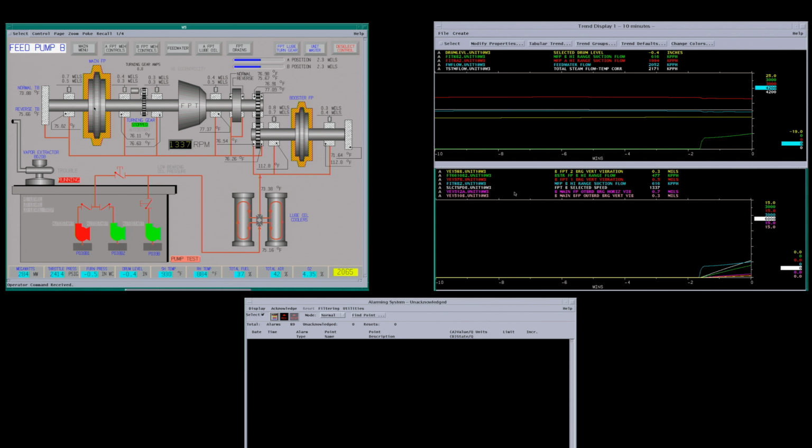I'd say the main feed pump has a trip at 3,400 PSI on it. If the pressure got that high, it would protect the piping. Most of the water went to the boiler. Then there's a separate booster stage that ran the higher pressure for the sprays, for the superheater sprays.